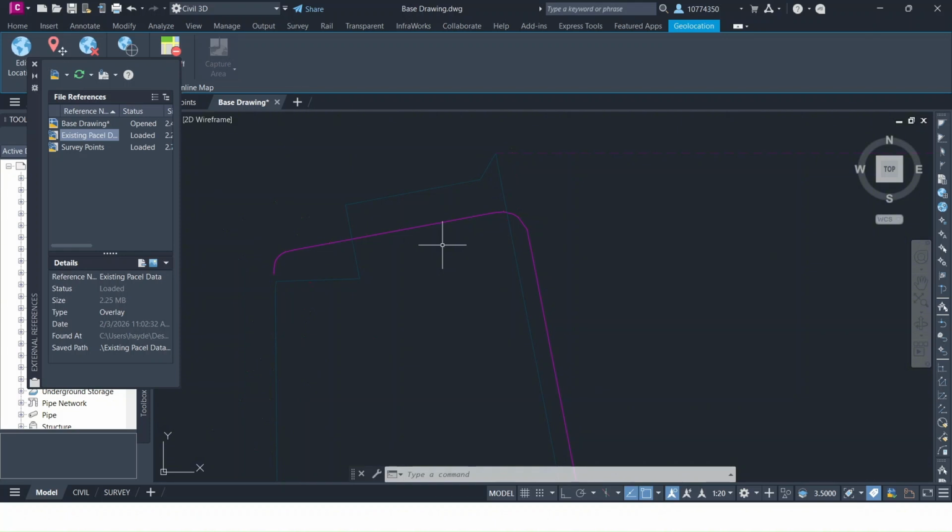The only way to fix that is to go back into your layer properties menu, find that particular layer, and check it off to unfreeze it, and it just becomes a huge hassle. So X references are so much better, so much easier. You just unload the thing, and then you go, oh man, I need to see this again, and reload it back in. That's my little spiel on that. X references are super nice.